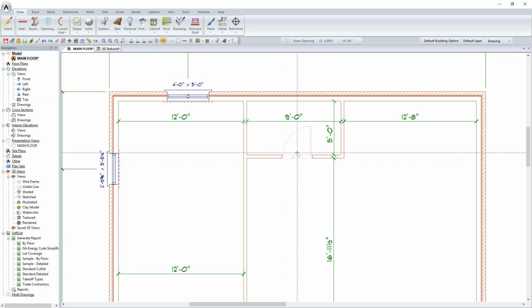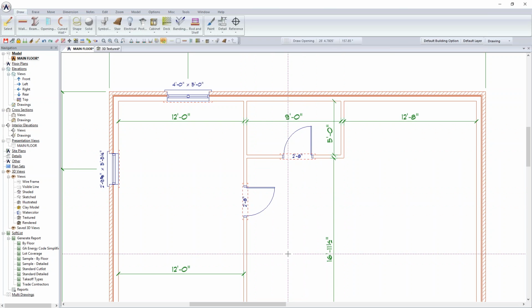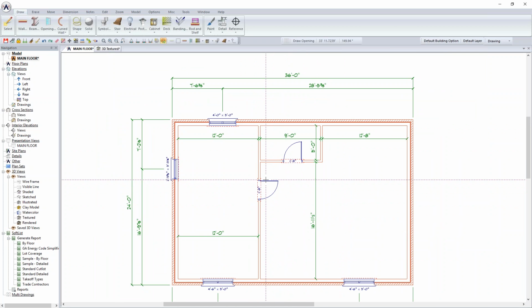Okay, so we're really just establishing left or right, reverse or non-reverse type door. And this is all done just by moving your mouse. I position my cursor where I want the door to be placed, and it's going to draw that 32 by 80. This is now a right-hand hinge door. Again, I'll do the same thing here, but this time I'll move my cursor to the outside, and so it's now, in my opinion, a right-hand reverse door, because of which way I move the cursor.